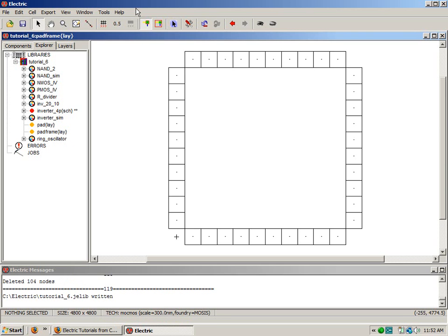So that's our nice pad frame, and we can see the size there, but let's go ahead and measure it. So I press the toggle distance and just eyeballing it, pulling it over. It's roughly 4,800. You can keep going. To get out of this mode, you can press this again. The measurements show up. To get rid of the measurements, go back into mode and hit escape twice. Or you can press M, and that gets you out of the mode and back to the cursor, click, zoom, wire. Okay.